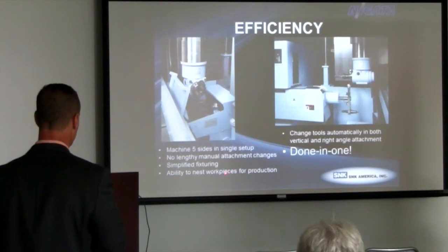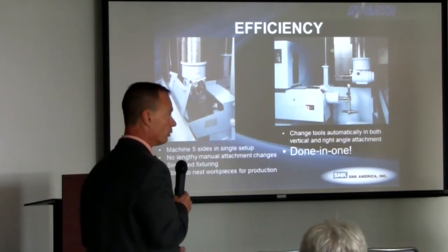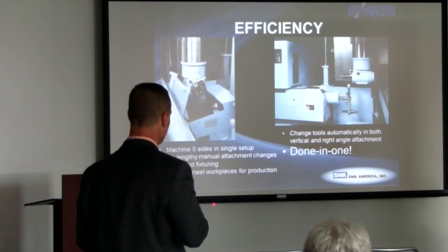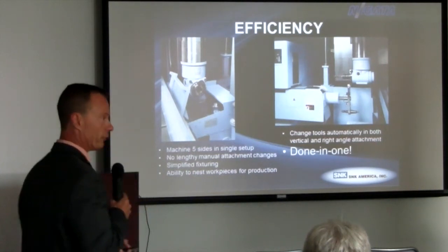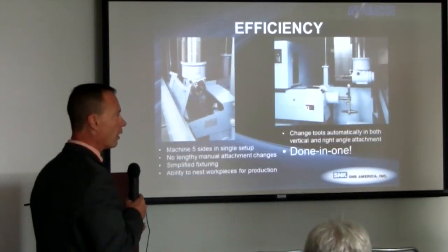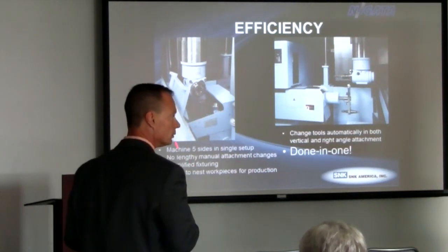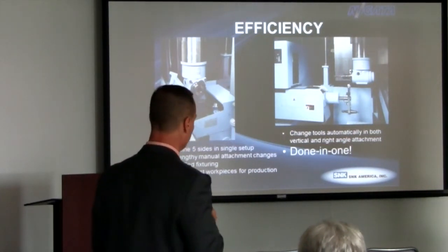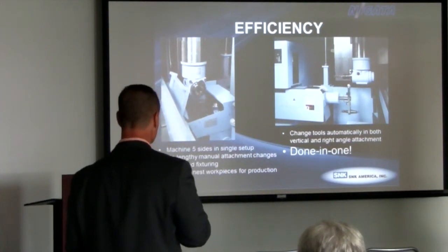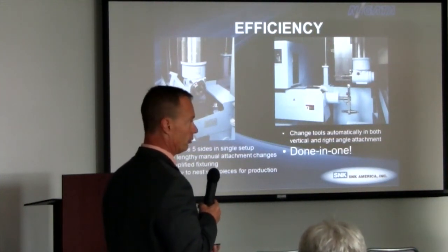One other note I want to point out: simplified fixturing. Putting a large part down onto a double column machine, versus a horizontal boring mill, allows us to dramatically simplify the workpiece clamping. If you're trying to hold a part up onto a fixture plate on a right angle plate or a tower on a horizontal boring mill, you have to have obviously more clamping, potentially stronger clamps. It's a longer process and the fixturing can become more complex. This is an easy way. Put the part down, let the weight of the part itself help seat it on the locators, and do some simple clamping.